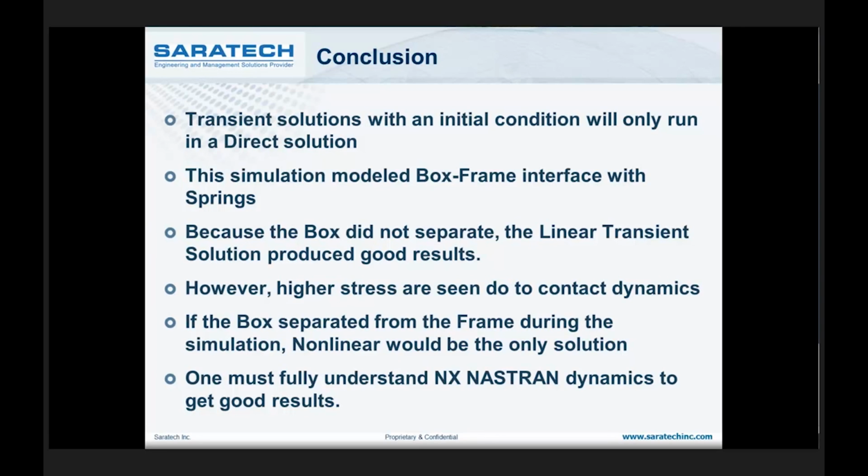Then you need to run over here and run the nonlinear. And again, one other caveat I'm going to leave you with is one must fully understand NX NASTRAN dynamics to get good results, because we had to do some dynamic assessment with springs and choosing frequencies and choosing damping and choosing time steps to get good results. So keep that in mind when you're running dynamics. And so I'll turn it back over to Emmy.